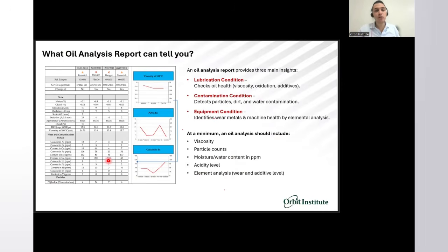The oil analysis is going to give you insight on the lubrication condition, the oil health, the viscosity of the oil, the amount of oxidation, the additives of the oil, whatever. Second insight is about the contamination condition, which is detecting any dirt or any water contamination. The third insight is giving you information about the equipment condition.